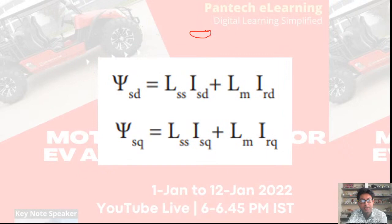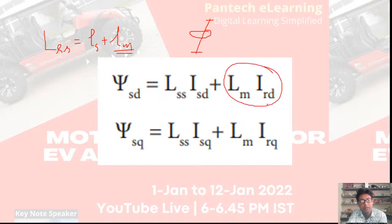this is the flux equation of stator. Yesterday I told you, here I have used LSS. This LSS is self plus mutual. As here we know, some portion of the flux will be influenced by the rotor current, so that is contributed by mutual inductance.